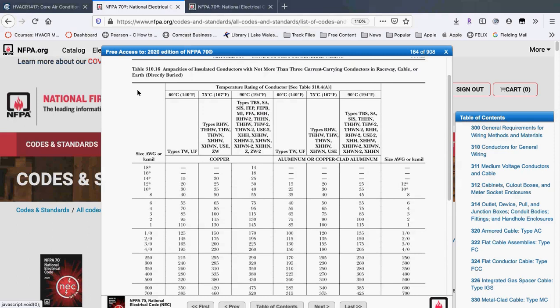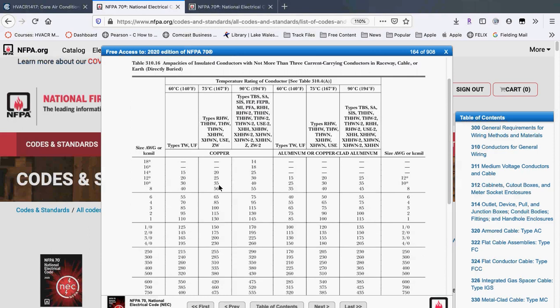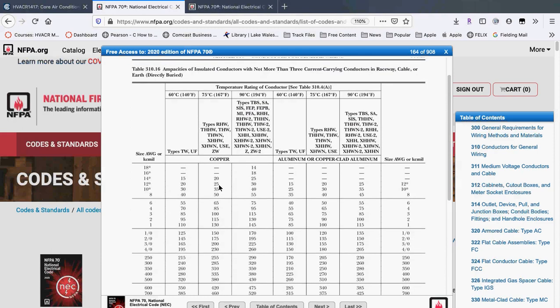Now, probably the chart you're looking at, Dylan, I think you're the one looking for the chart, comes pretty close to the one I have up here on the screen right now. This one actually breaks it down into pure amperage. If I'm looking at copper wire, that's THHN wire, which is the majority of the copper wire we use. You said THHN? THHN.